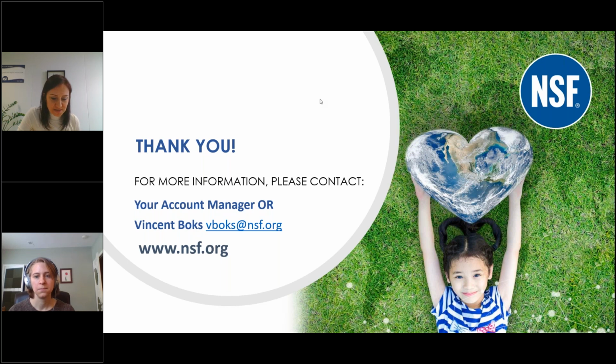Okay, thank you. And I'll choose one last question. What is the difference between the Q statistic and the NSF ANSI CAN 372 lead content tests? Great question. It's important to differentiate. The test with the Q statistic is about lead leaching from faucets, where we are testing how much lead leaches from the faucet into drinking water. NSF ANSI CAN 372 is a lead content standard.